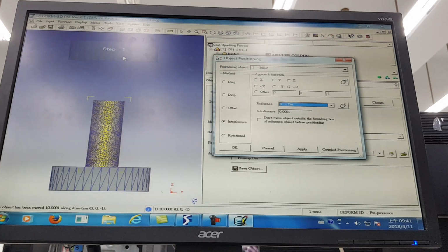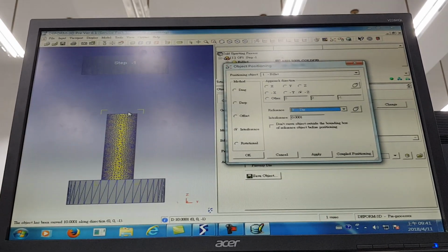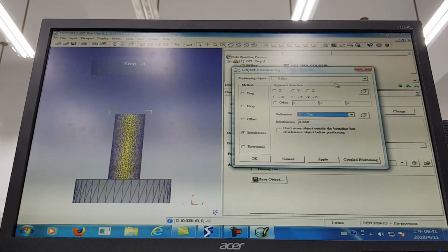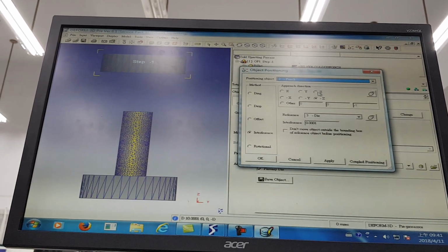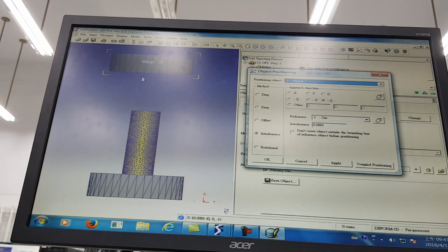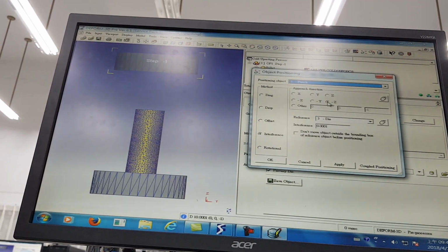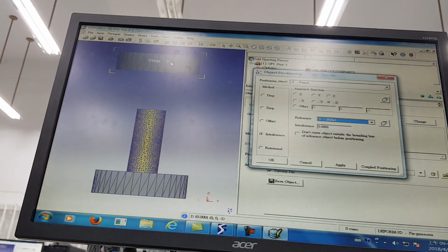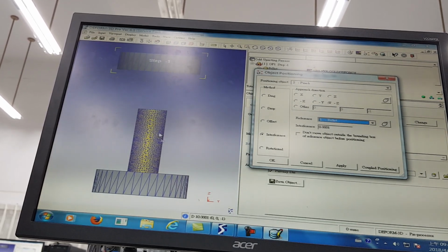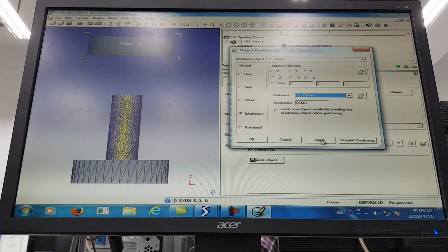And right now, we need to move the punch down to contact the billet. So here is also move punch. Select punch, and also they will go down, so you choose negative Z. And the refer is by billet because punch will touch billet, not touch the die. And you click apply.